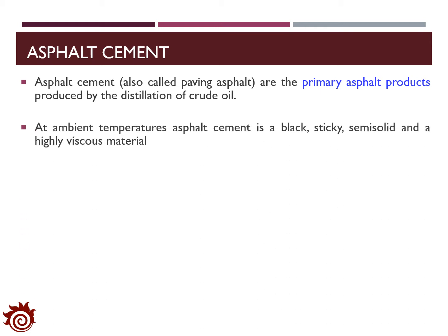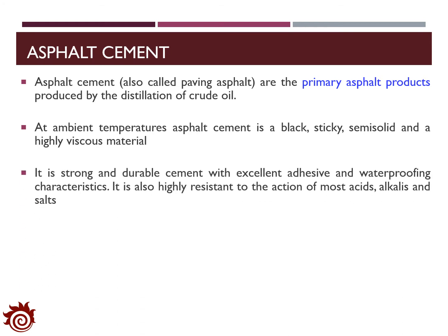At the ambient temperature, asphalt cement is a black, sticky, semi-solid, and highly viscous material. There are actually a lot of properties of asphalt which make it suitable for road pavement. It's strong and durable with excellent adhesive and waterproofing properties, and is also highly resistant to the actions of acids, alkalis, and salts.